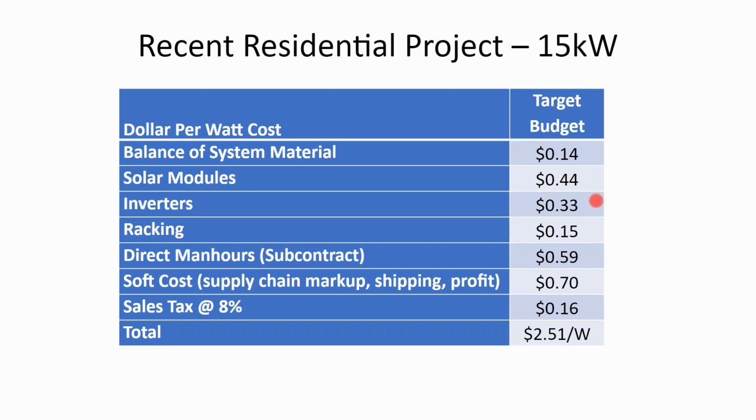Inverters. Inverter pricing can get cheaper than this, and sometimes that's warranted. Generally, when I'm buying inverters, I'm personally looking towards batteries, and so this is the price of a solar inverter that might have some limited battery backup option, like the very popular grid-tied SolarEdge system. But a pure batteryless inverter you might be able to find for 25 cents a watt. I'm also including module level panel electronics called microinverters or DC optimizers, which have their own slides to come in this price range.